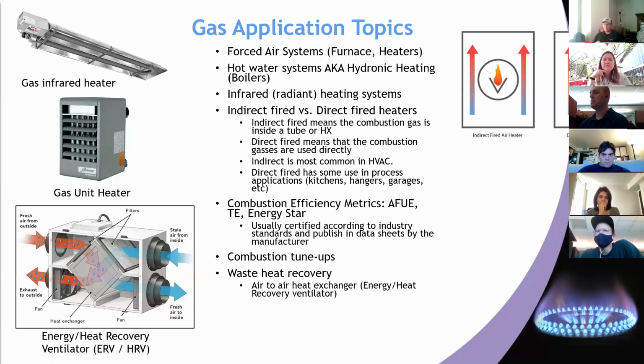A lot of times when we're working with a boiler or a furnace, we'll ask, how often is your furnace tuned up? How often do you do a flue gas analysis test to verify the combustion efficiency has not departed from what it was when you installed it? This is something we're really hoping to get you all experience with.